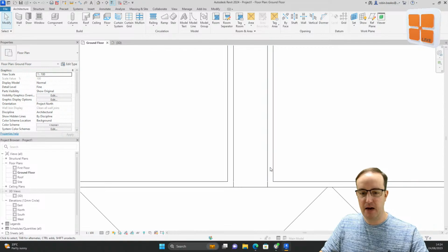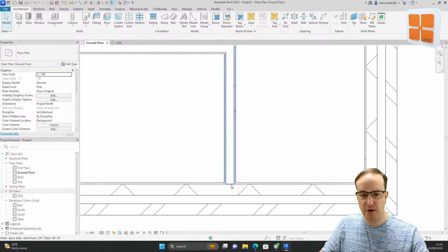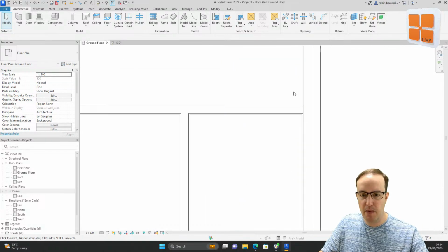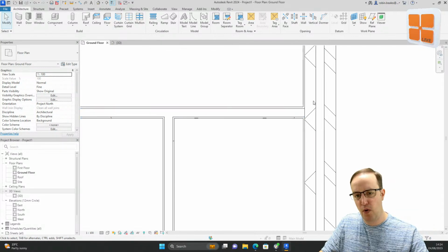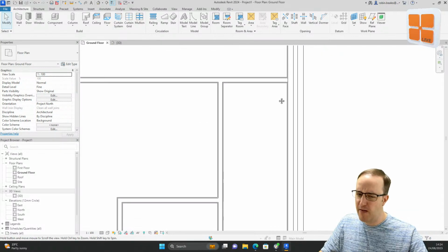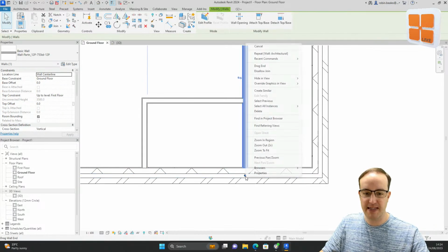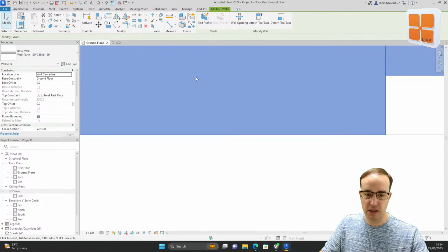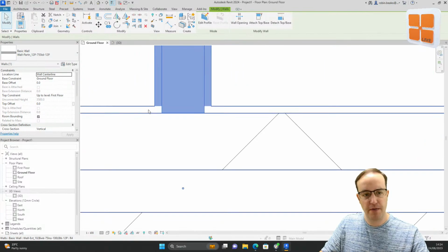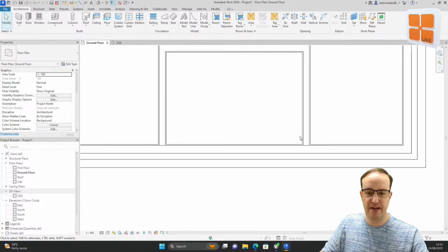Because of these materials, Revit knows how to wrap things like the plasterboard here. So it can wrap the plaster around, it knows to join the cavities. If we had a block wall, it would join the block work. Revit does a really good job of doing those joins for you, which, should you want to, you can disconnect the joins. So we can disconnect them so it was just a single piece of plasterboard rather than wrapping, but you know, again, it's down to you.